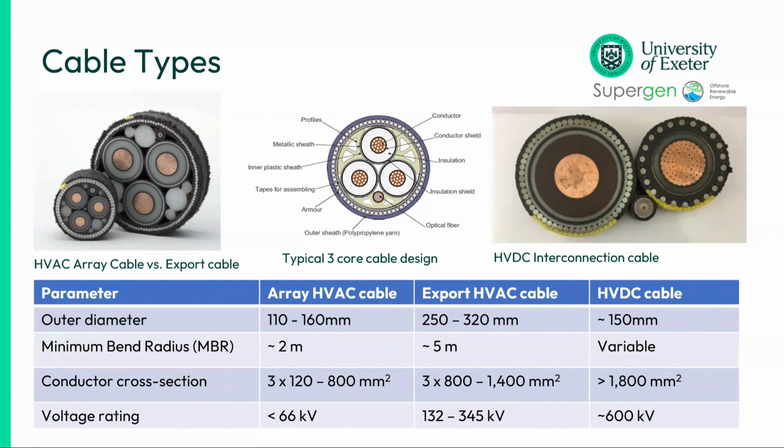But it comes down almost to some of the basic engineering principles, because on the bending stress, a lot of focus is on the conductor, but the conductor is in the center, or close to the center at least. So it'll see some of the lowest bending stresses just by sheer position, because of the second moment of area. Whereas the layers further out will see higher bending stresses, which is one of the challenges. If you look at the outer diameters, if you go to higher voltages, which is the drive, you need more insulation. You need a larger cable. Larger cable, higher bending stress.